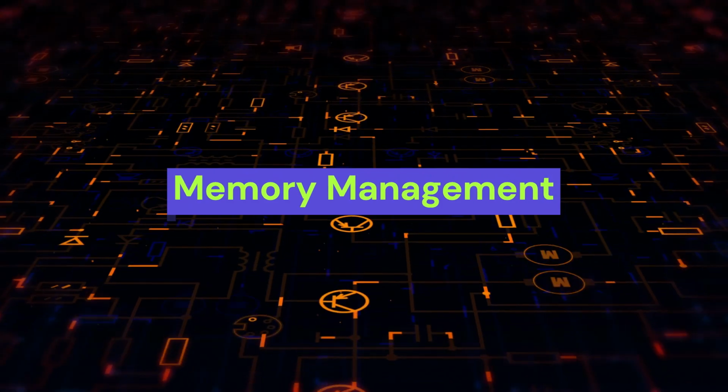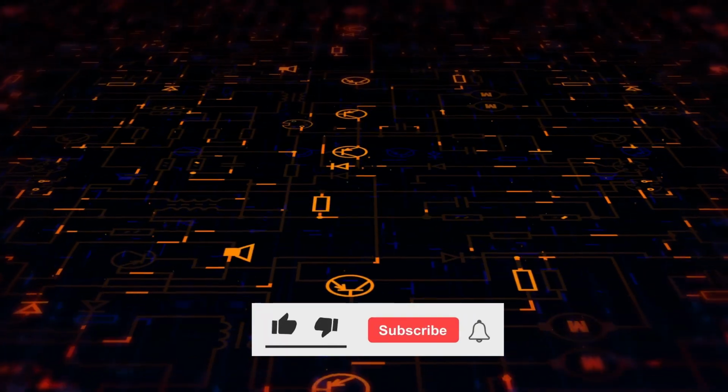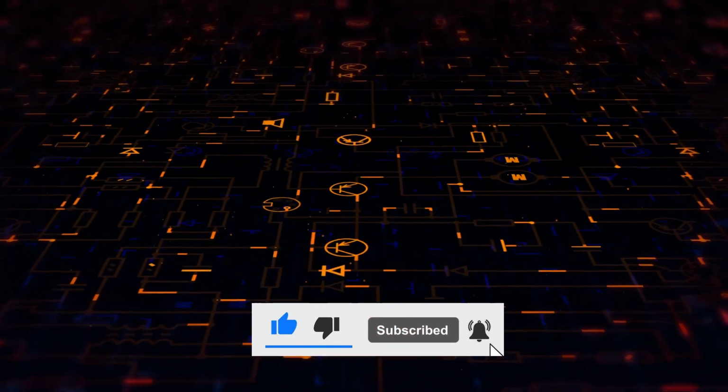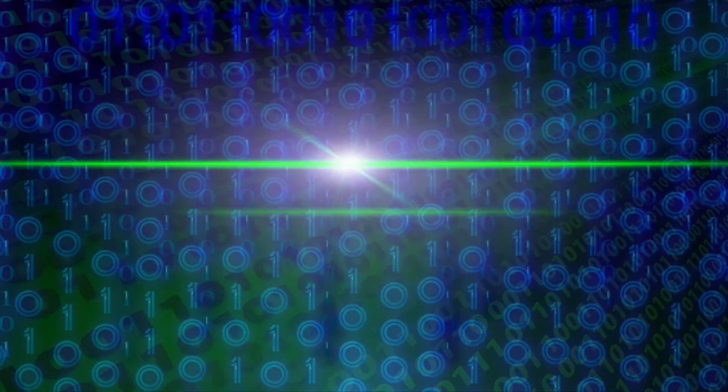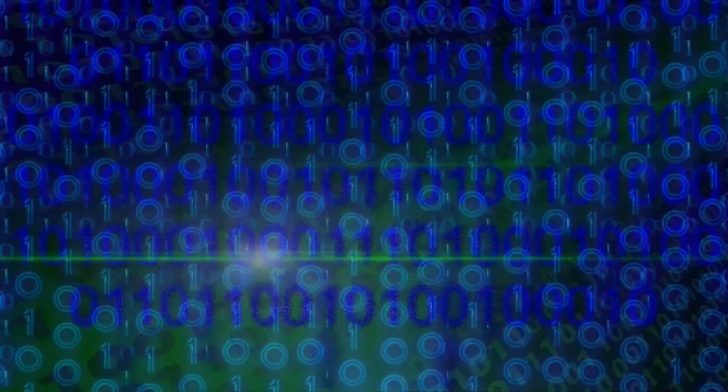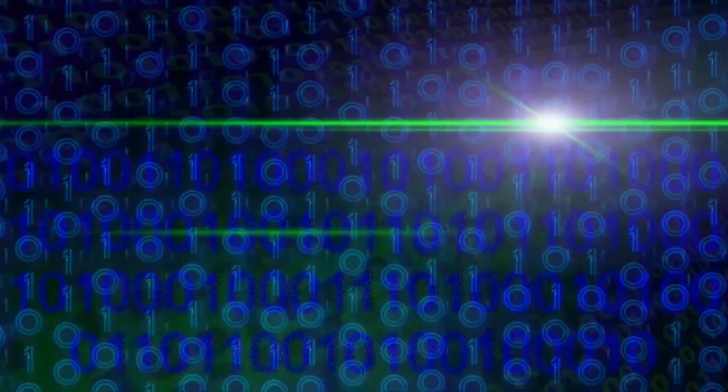Memory management. Memory management in embedded systems involves the efficient allocation and utilization of various types of memory resources, including RAM, ROM, and non-volatile memory, for example EEPROM and flash memory. RAM, random access memory, is used for temporary storage of data and program instructions during runtime. It is volatile, meaning its contents are lost when power is turned off.